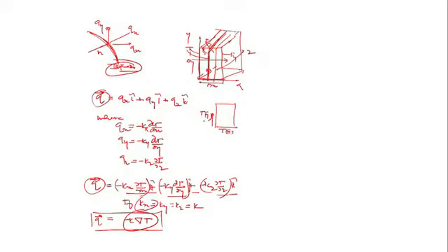So how can I make it one dimensional? By considering that the variation in y and z is very small and can be neglected. We only bother about temperature variation in x, because the thickness of the wall in x is very small compared to the other two directions. This is how I simplify our problem from three dimensional to two dimensional and then to one dimensional. Now here I have kx, ky, kz.